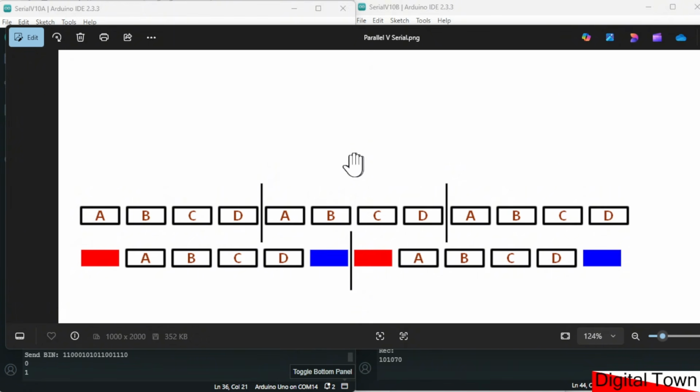Now think of these as a data sandwich. You've got your top piece of bread, you've got your filling, which is your data, and then you've got your bottom piece of bread. And these come over in a set order. Now the way we do this is we give the start byte, the one side of the packet, and the last byte specific values.